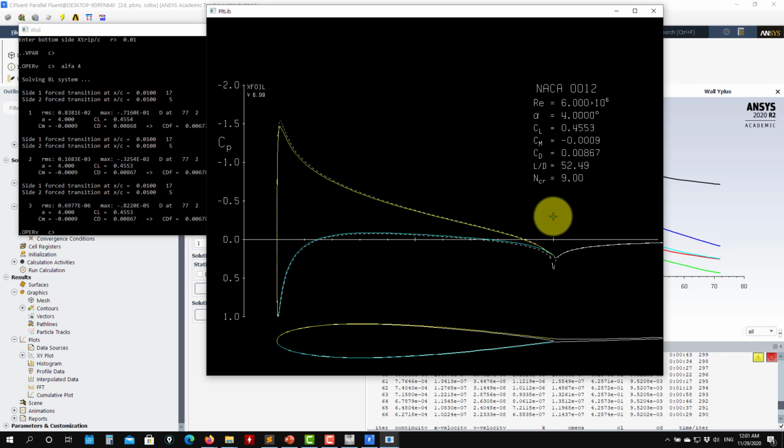See that resolving the transition or having a fully turbulent boundary layer changes the coefficient CD in particular a lot. CL is not a problem; CD is difficult to compute. Usually we know 2 pi will be the CL slope, then we have the correction for wind. So computing CL in general is easy. CD is very tricky, and there is a strong dependence on the transition to turbulence, and this is very important. CFD data tends to correlate better when you have a fully turbulent boundary layer.